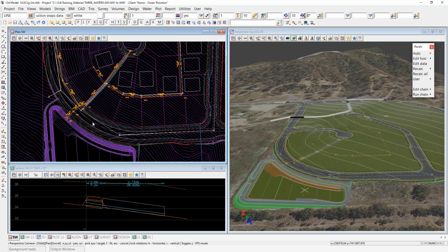In other scenarios like big highway designs, such as a dual carriageway, your reference string may not be within the carriageway, or might be right on one edge of one carriageway, and it might be over the top of one of your set-out strings. And you do want a little bit of horizontal separation between the set-out string and the center string. There's not a great solution at the moment.